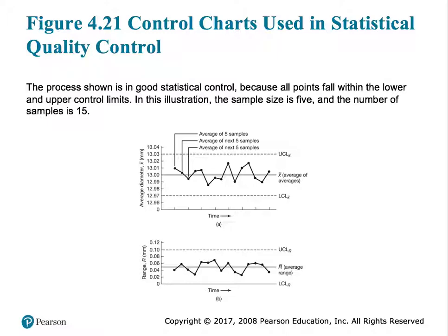For those of you who have done statistical process control, or SPC, or statistical quality control, you will see that you plot these numbers and you have an average value, and your process should tell you whether or not you should exceed it by 1 sigma or 2 sigma. If it is above 1 sigma or 2 sigma, that means this part cannot be used and it has to be scrapped.